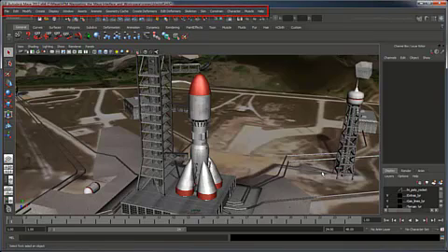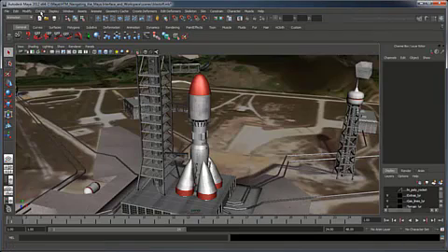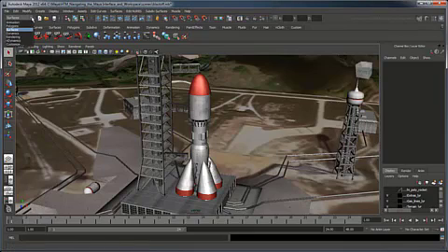You can access many of Maya's functions from the menus along the top of the application. Some of the most commonly used menus, such as those to create objects, are always located here. The rest of the list changes depending on which menu set is currently active via the Menu Set drop-down list. Menu sets are organized by common workflows, such as animation, modeling, dynamic simulation, and rendering. If you ever have trouble finding a certain menu, the first thing to check is that you're in the right menu set.